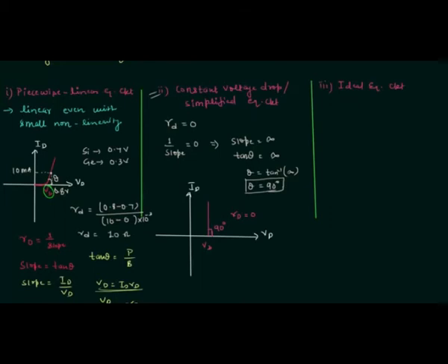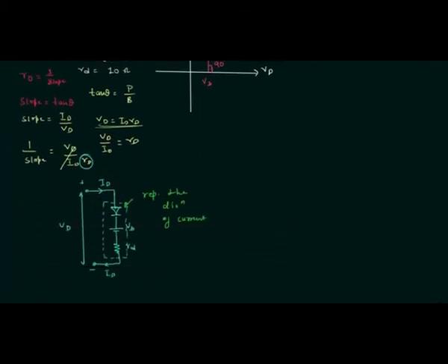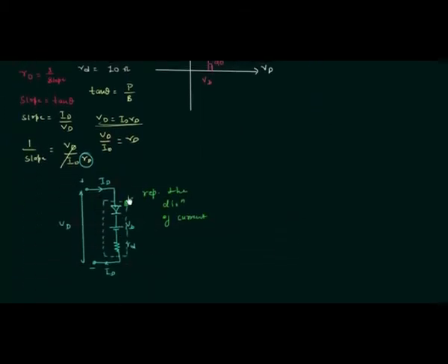Now we will make the equivalent circuit, and it is very simple. If we compare the equivalent circuit with the first model, we will find there is no diode resistance. So everything will remain same, and we only have to remove the diode resistance. So I will draw it quickly. First we will make ideal diode to represent the direction of current. This is the ideal diode.